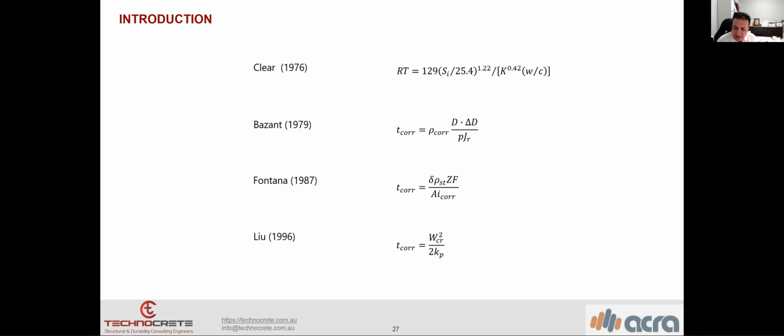The other thing is the life of that material as well. If it's steel, then we have to maintain that steel as well. For example, let's say every 5 years it has to be sandblasted and painted again in order to prevent corrosion. That steel strengthening needs to be maintained as well.